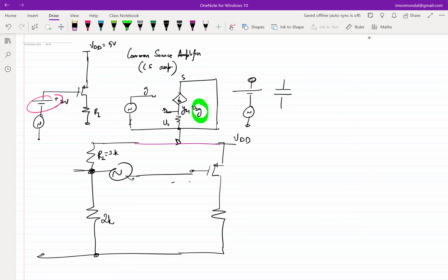When you are doing this, if you think of 2 cases, the case that you will be familiar with is the ESC201 lab, when you have a single source. You have this big box. Only one side of the box gives you the signal, the other side is internally grounded. All the sources, regardless of whether it's a power supply or a signal source, one side has to be internally grounded. That's a practical consideration. The other problem is, let's say this signal source is not a pristine source that you are pulling from a box.